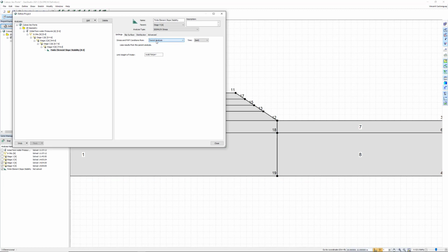Compared to a traditional Slope W limit equilibrium, the finite element slope stability analysis doesn't need to iterate to find interslice stresses that will ensure the factor of safety is the same in all the slices. Instead, as the stresses are known, the resistance is directly compared to the solicitation and a factor of safety is locally computed in every slice. The overall safety factor for a slip surface is determined by integrating the shear resistance and mobilized shear along the entire slip surface.